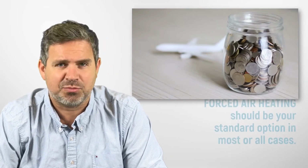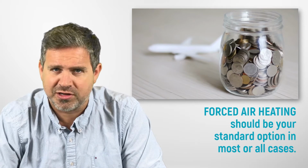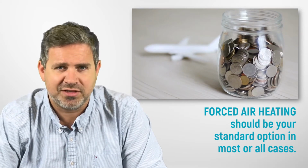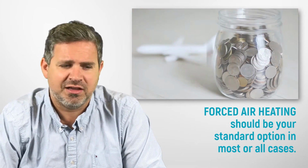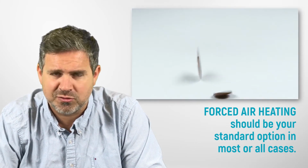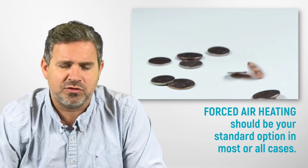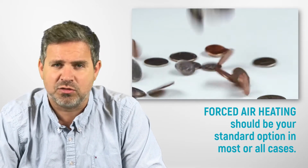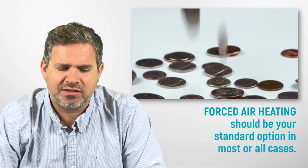Negatives and positives, pluses and minuses. I would say forced air heating, especially in terms of pricing and cost, a lot of times is going to be the best bang for your buck. A forced air furnace is relatively inexpensive compared to a whole house full of ductless heating systems. It's way less expensive than electric baseboard heating in terms of operation. It's way less expensive to install as compared to hydronic heating or boilers. So what it really comes down to, it's more cost effective.